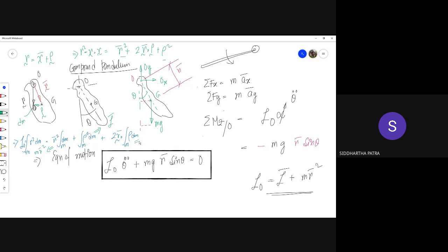And in the third case, integration rho dm is basically rho bar times m. That is how we define center of mass. So we take the position vector of a differential mass, we integrate that over the mass. That basically gives me the average position, or the location of the center of mass, times the mass.